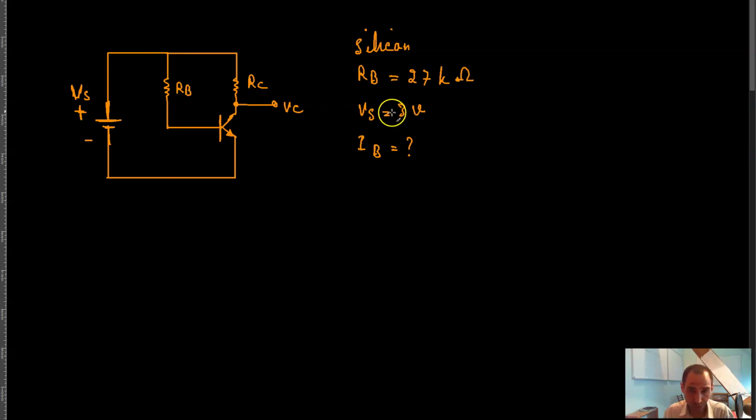Now when you're solving these kinds of circuits, it's important to note what sort of voltage you have here. If the voltage is under 10 volts, as is the case in this particular case, then of course the voltage drop across your PN junctions becomes important, because it is a large portion of the supply voltage.